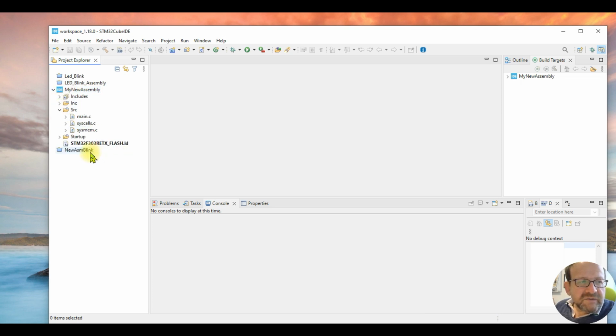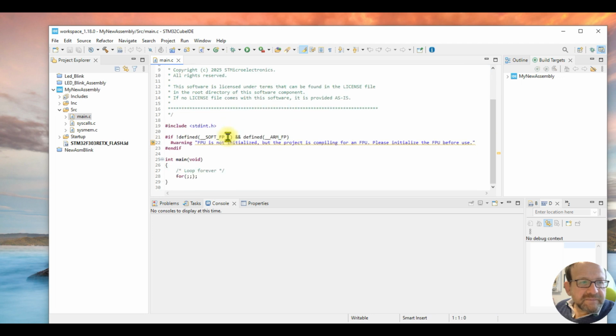What we're going to be concentrating on is the src. It's going to be main.c. It's basically empty for now, and we're going to be using it empty also. So we'll have a while loop that's going to continue to call an assembly procedure over and over again in a loop. So this is how the interaction is going to work for us.